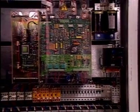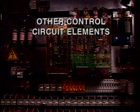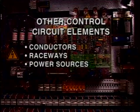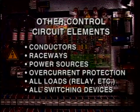The elements of a control circuit include all the equipment and devices which are involved with the function of the circuit itself. These elements also include conductors, raceways, source of energy supplying the circuit, overcurrent protecting devices, all the relay coils, contactors, and starters, as well as all switching devices which govern the operation of the machine or process being controlled.